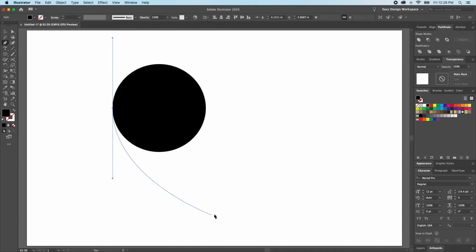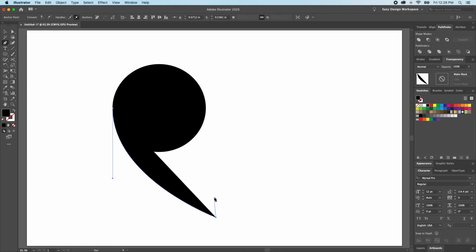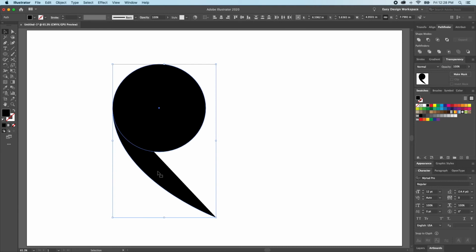Let it go, and then you can see what it's going to do. It's showing you where that line is going to go. So I want to come a little bit past the right side of that circle, and I'm going to click. Type a V. I'm going to drag across both of those pieces. I'm going to type the O for the Reflect tool, and I want to find where I want the center of this heart to be, and I'm thinking I kind of like it right around here. I think that'll give us a good dynamic Valentine heart.